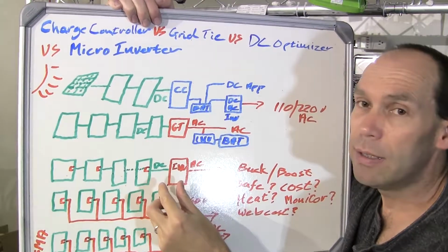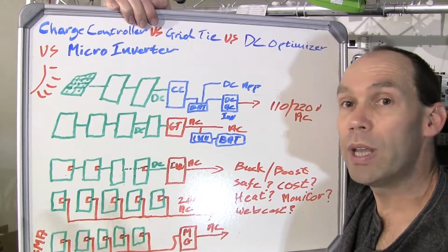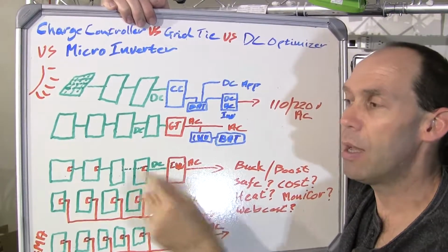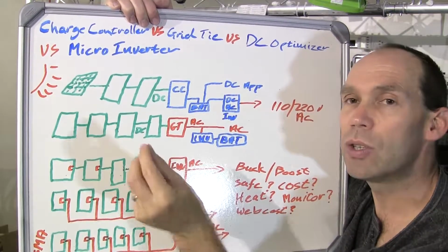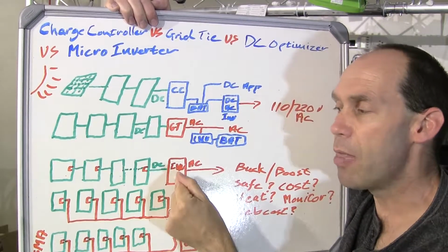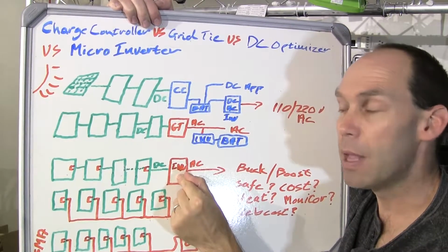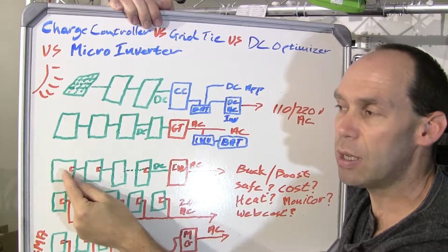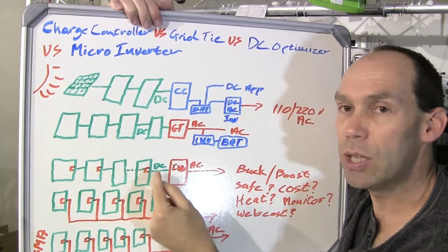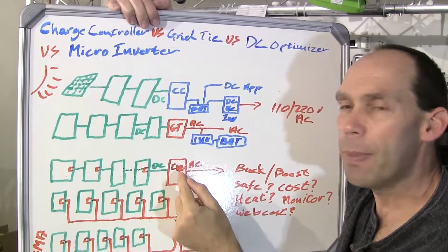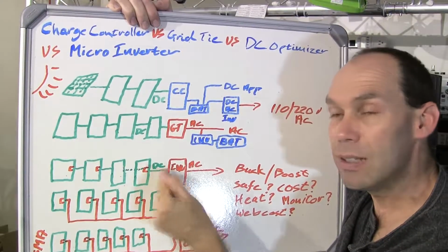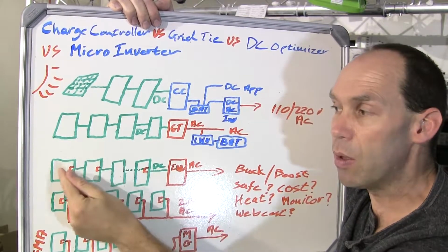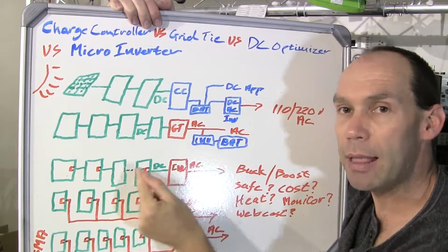Now, in certain of these setups, let's say for instance you've already got a grid tie inverter, some of these technologies you can just go and add on to your panels and they'll work with your grid tie inverter. But the other types of these technologies, where let's say they're doing more specialized MPPT at each of the panels, they require an inverter where they've got a single voltage input because the MPPT work is being done at the actual panels.